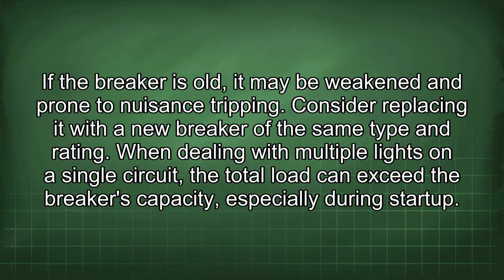If the breaker is old, it may be weakened and prone to nuisance tripping. Consider replacing it with a new breaker of the same type and rating.